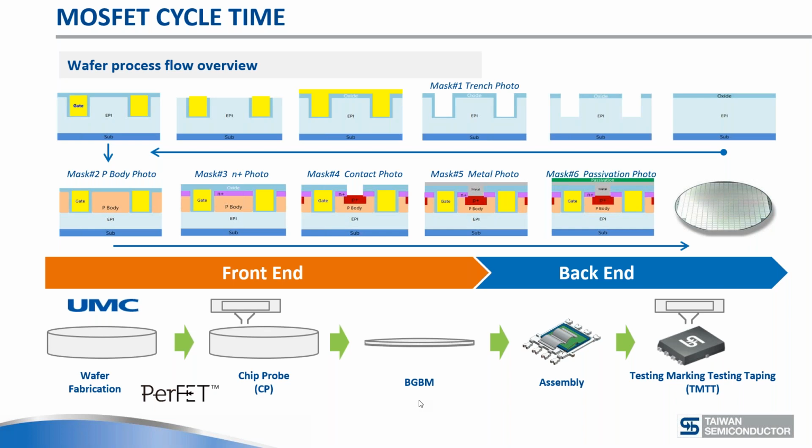So you grind the wafer here, make it thinner here to improve the RDSON here. That's another step that might take 2 weeks or something like that. And then you go to the back-end assembly, 2 or 3 weeks here. If you look at the MOSFETs here, we've already talked about the front end quite a bit here.